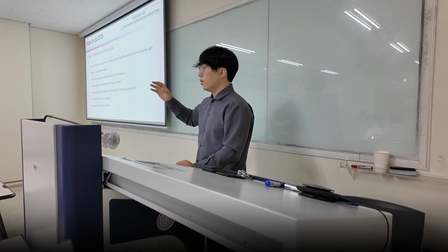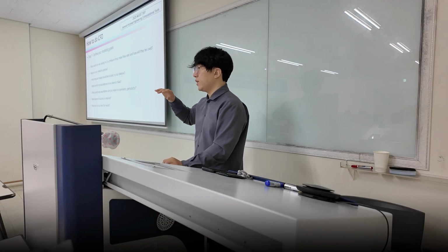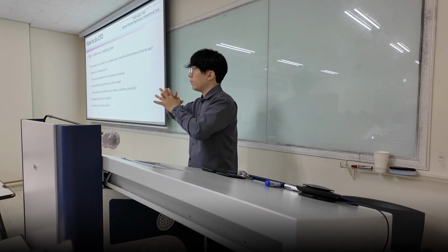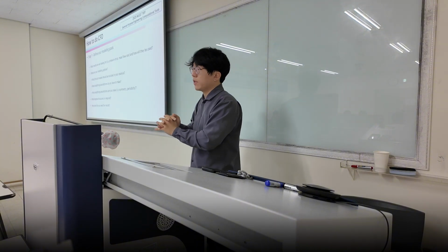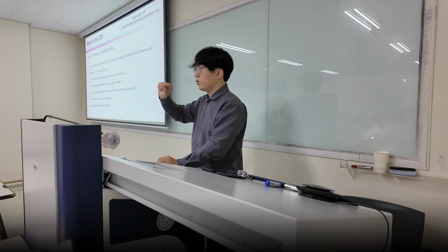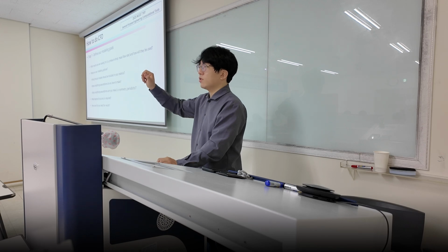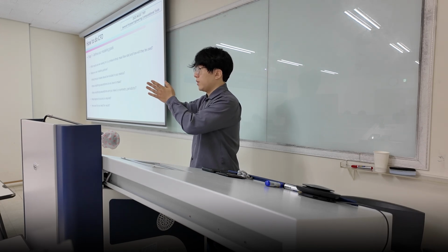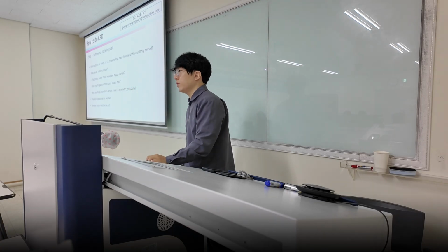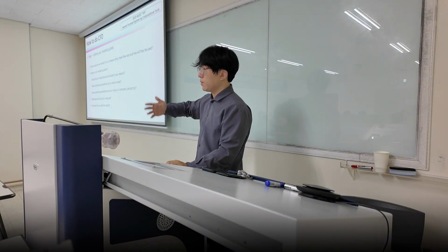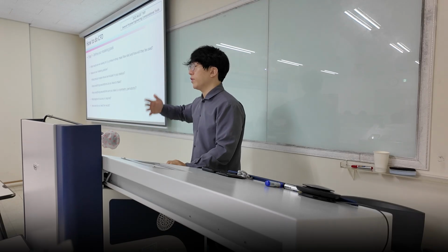So what we mean by mesh independence analysis here is, when you're increasing the number of mesh, usually at the order of 1 million to like 10 million, the results tend to converge, and then you're going to see almost identical results over a certain value of mesh, let's say like 15 million mesh, and that's going to be the minimal amount of mesh you need for the numerical analysis.